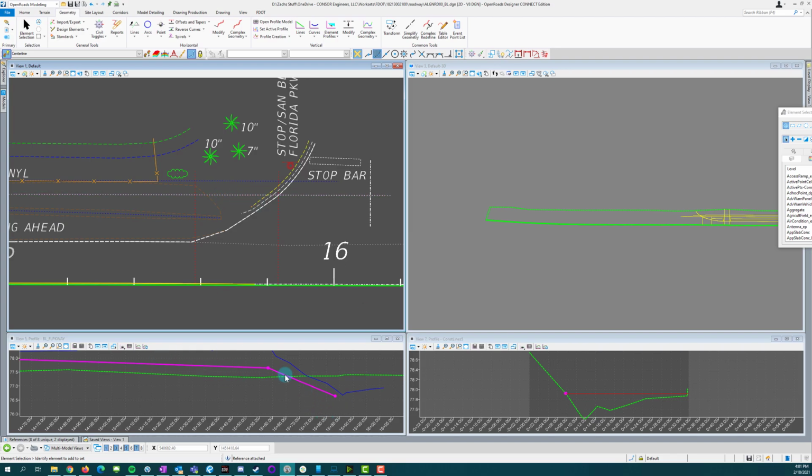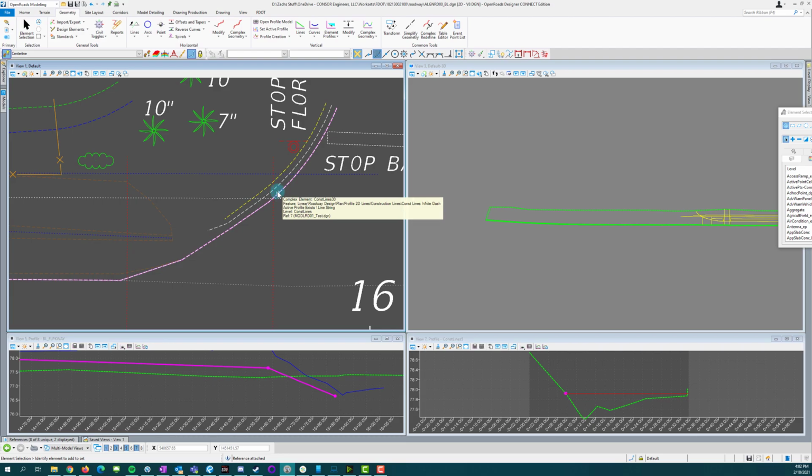Your back of sidewalk profile should reflect the usage of a ramp, and you can look at the index to figure out what that's going to be. You might want to model in here the curb, and then the gutter and then the back of the curb and build in all of these points. Then I need a ramp and a landing here. So that will affect your profile.